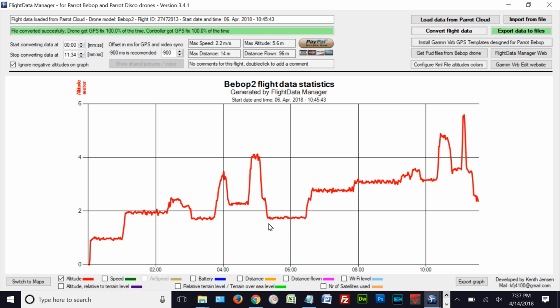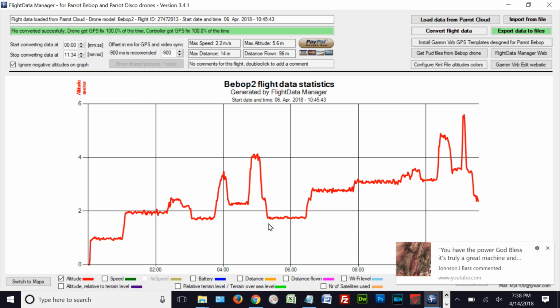So what I said earlier is I looked into the difference between taking off FPV and allowing the sonar sensor to establish the altitude, and of course we don't get good readings there. Whereas when we use a flight plan, I usually bring it up about 10 meters and then switch on flight plan, and apparently when I switch on flight plan, something takes place that makes it accurate after that.